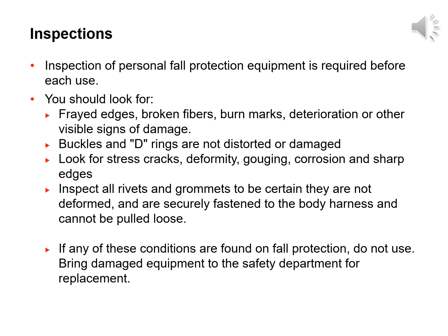All fall protection equipment must be inspected before each use. Before you use a harness or lanyard, you should examine them for defects. For body harnesses, you should thoroughly inspect all of the nylon webbing for frayed edges, broken fibers, burn marks, deterioration or other visible signs of damage.